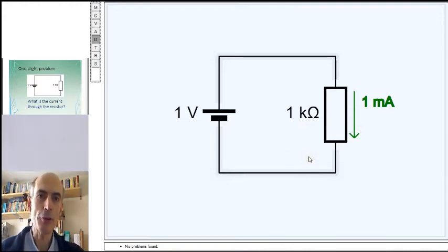What might surprise you is to learn that if you put this circuit into just about any analog simulator in the world, it would fail to solve it and give you an error. Why? Because most analog simulators just apply nodal analysis. And something interesting happens when you apply the step-by-step instructions for nodal analysis to this circuit.